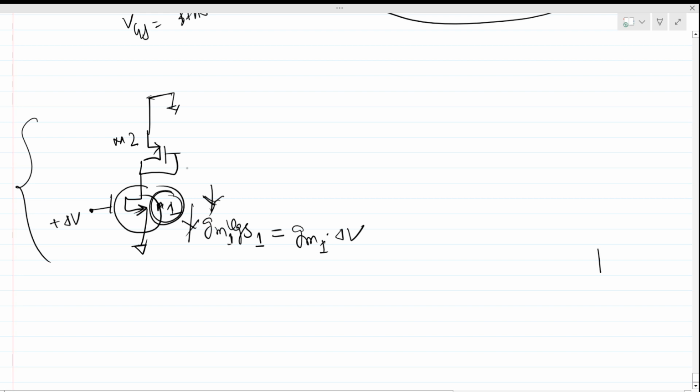We know that the small signal model of PMOS and NMOS is the same, and we are neglecting rout here. The channel length is neglected, so the lambda value is 0, and we are not considering the output impedance, for easy calculations.